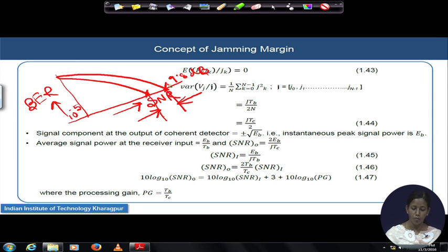it is a function of the design of the sequence itself, because if you lower the TC, the processing gain will increase and the graph will keep on shifting towards the left, and your processing gain will keep on increasing. But remember, whenever you are increasing the processing gain, somewhere you are having some loss, at the cost of something.